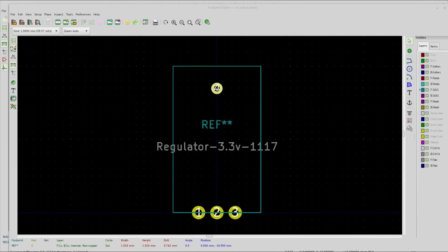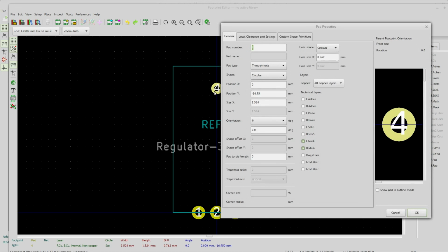So then the big trick is we want to take this regular through hole feature pad, and we want to turn it into just a plain old hole in the board, something we can screw something into. Now, if you wanted to have contact from one side of the board to the other, then yeah, you would leave it as a through hole because it gets plated through the middle of this, and so then you would establish contact from top to bottom. But in this case, let's say that all we care about is making a hole through the board.